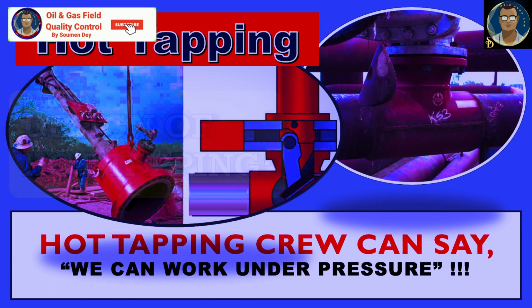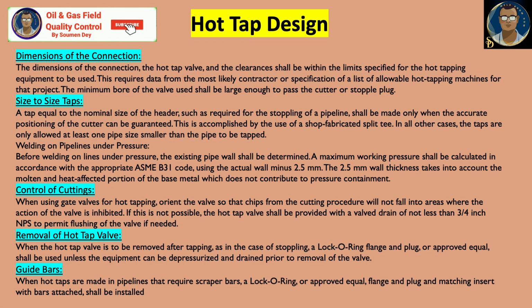Hot tapping design. Dimension of the connection. The dimensions of the connection, the hot tap valve and the clearance shall be within the limits specified for the hot tapping equipment to be used. This requires data from the most likely contractor or specification of a least allowable hot tapping machine for the project. The minimum bore of the valve used shall be large enough to pass the cutter and the stopple plug.